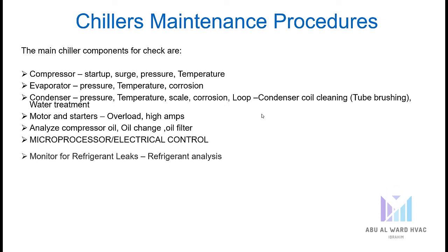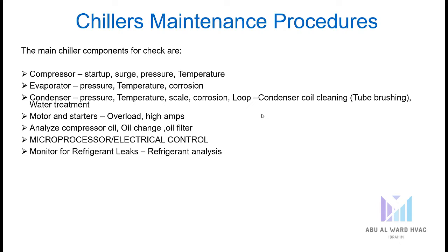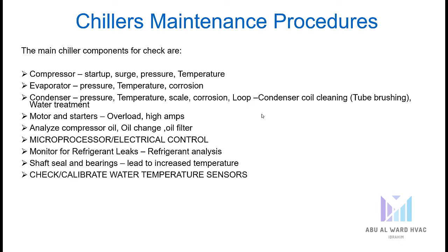Microprocessor electrical control. Monitor the refrigerant leak in case there is a leak. We need to do the refrigerant analysis. Shaft seal and bearing wear lead to increased temperature. We need to calibrate water temperature sensors.